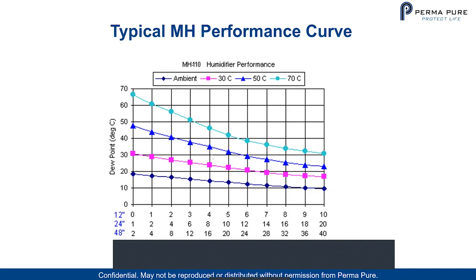Of course, this all depends on the amount of heat energy you're putting into the water to keep it at the temperature you need. Depending on what you're doing, you can control the humidity with water temperature, but what we've figured out in our own labs is how to control the humidity with pressure. In a future presentation, we're going to go over our new humidity generator that uses pressure as a principle to regulate the amount of humidity coming into the gas stream.